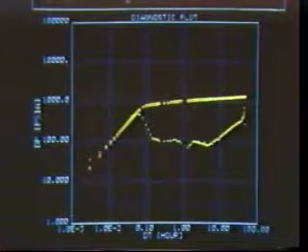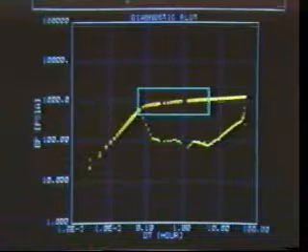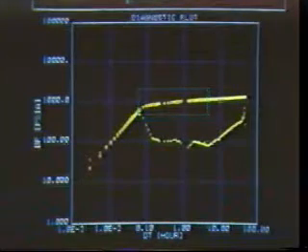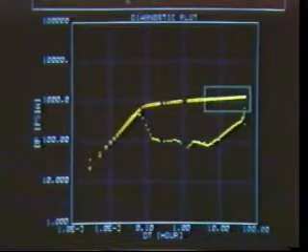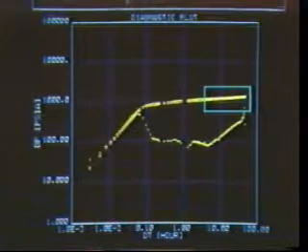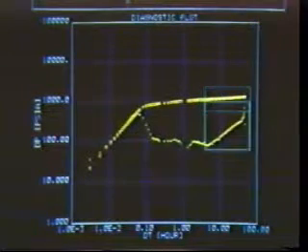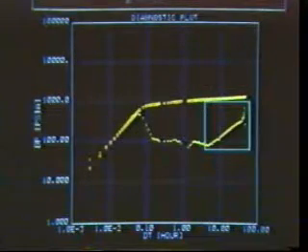Following the wellbore storage influence period is the infinite acting period, evidenced on the log-log plot by the straight line portion of the data curve. The boundary influence period is evidenced by a deviation from the infinite acting period. However, the boundary influence period may be undetectable on the data plot. It may only be evident on the derivative plot.